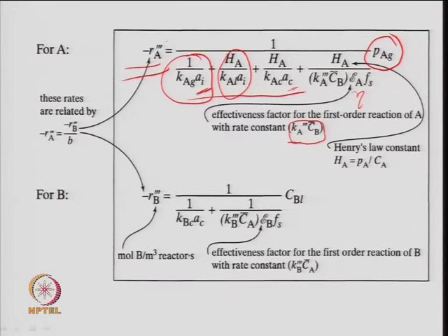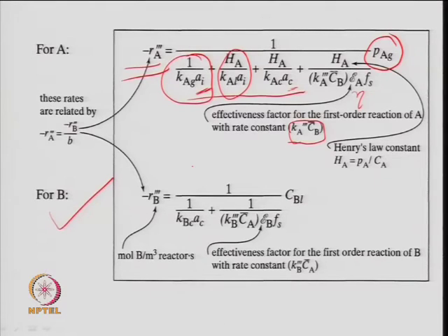And there is always a relationship between the rates. So, I told you that R A upon A is equal to R B upon B. So, it will depend on the stoichiometric coefficient. So, one can very easily write that if this much moles of A reacted, how many moles of B will react. So, one can very easily write down the expression for that also, right. So, just one is sufficient, because in design equation generally we write the rate of reaction based on limiting component, and one can very easily write down the reactor design equation, because this is the rate equation.